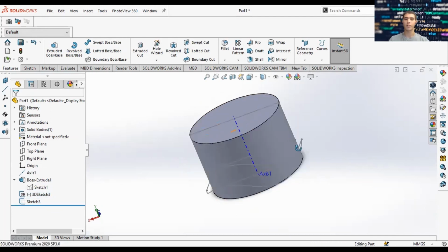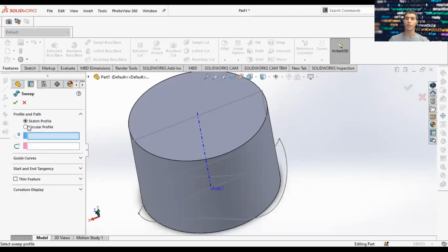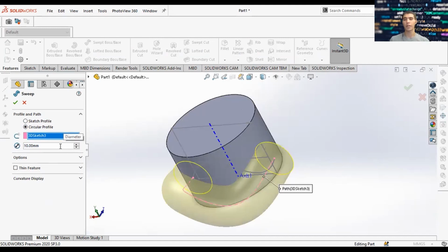So allow me to introduce you to the sweep function. The sweep function is basically going to take a sketch profile and sweep that sketch profile along a particular contour. And so we'll be using this sweep function to simulate the outer cuff. If you notice, the outer cuff reaches to 28 millimeters.